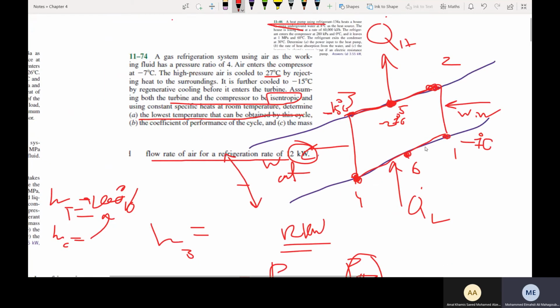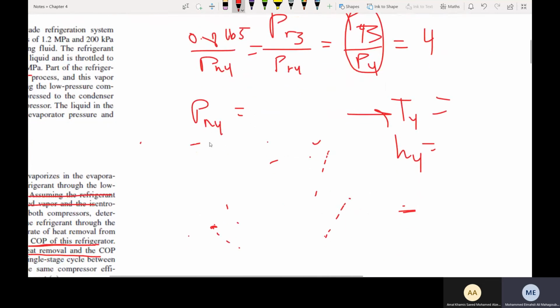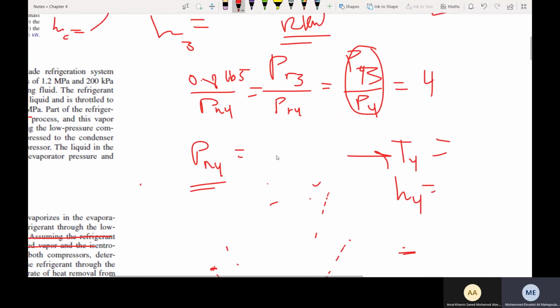So I have this. I want to go to point 1 directly from point 4. What I can do, I have QL here. I have the temperature here, of course, so I don't need to go through this process. Directly after I find relative pressure 4, let me find it because it's easy, as you can see. So it is 0.8405, which is approximate because I approximated the relative pressure. So the relative pressure of 4 is going to be 0.210. So find where 0.210 is.